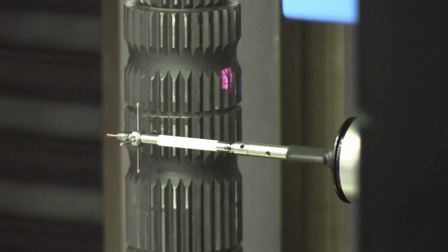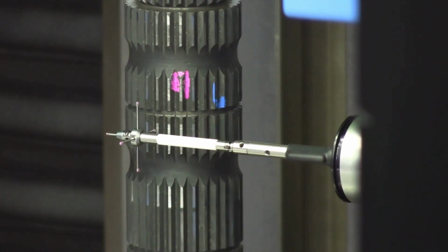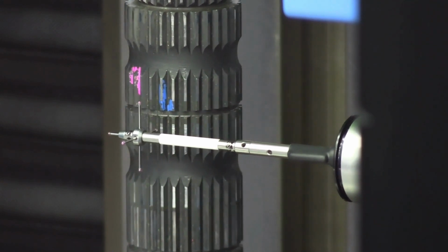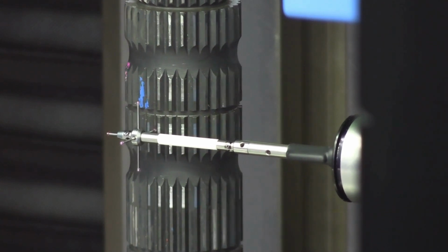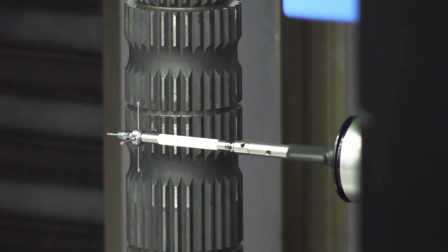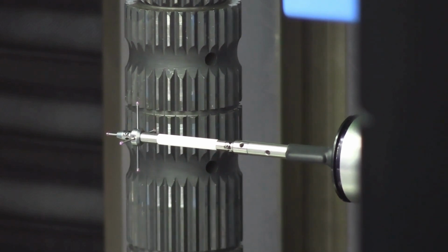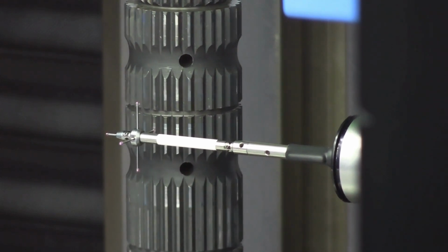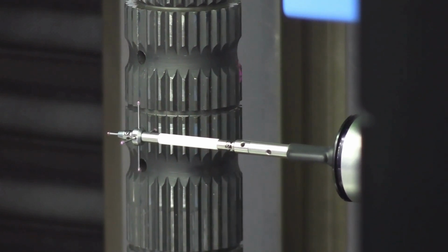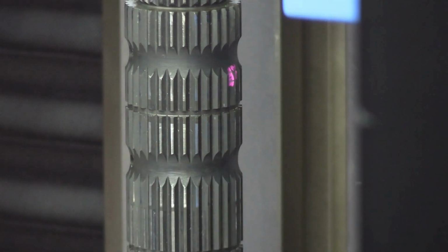One of the key differences of the Opticline system in comparison to other shaft scanning systems that may have a probe is that we've actually got the Y and the X-axis movement. Obviously with the optics we've got the Z. But it enables us to have a better contact point on some features, especially like a gear. The SM25 probes are designed to not have too much pressure in this orientation, the Y positive direction. The sensor is meant to be deflected in the other way, which is why it's quite beneficial for looking at these kinds of features.